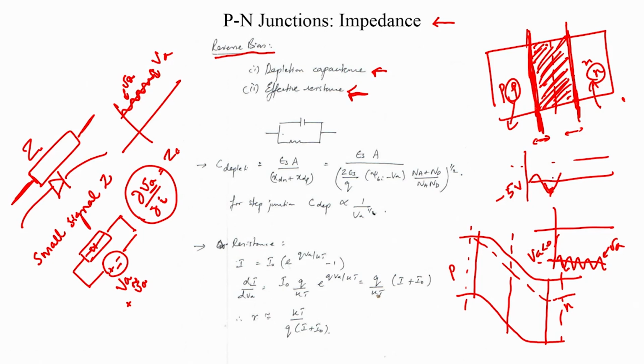So if the voltage is in this region, it is more reverse bias than 5 volts, and therefore the depletion region increases and uncovers more fixed ions, and then as it goes to 5 volts it reaches its mean depletion width, and as it goes slightly above 5 volts, then it covers some of the ions and it reduces in size, and it performs a little fluctuation, and it is this fluctuation that results in an effective fluctuation in the charge.